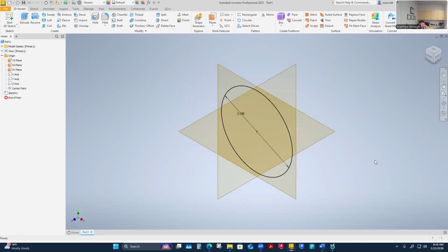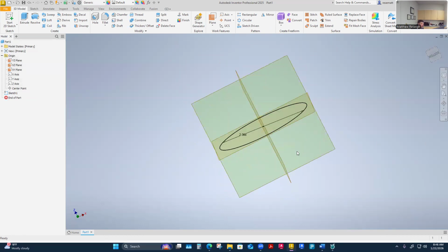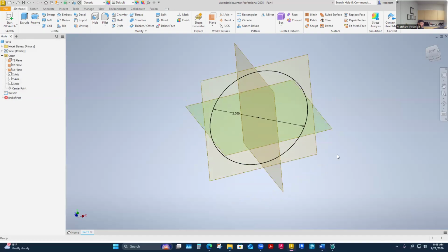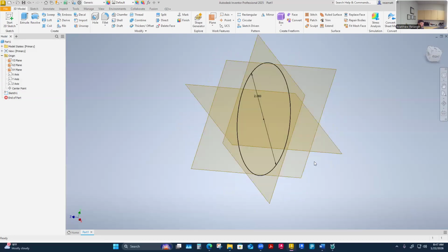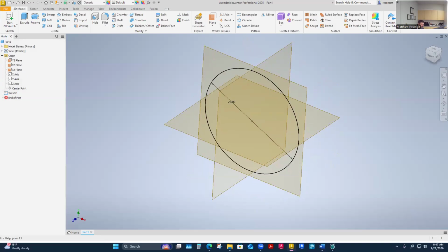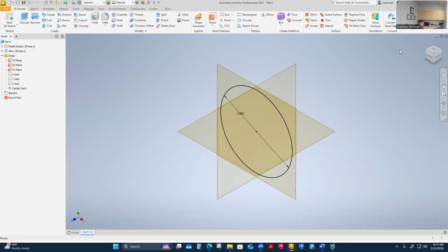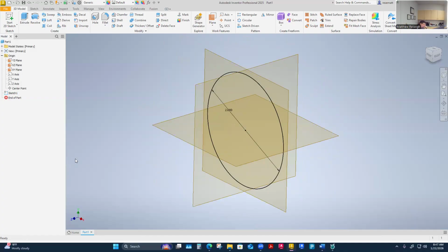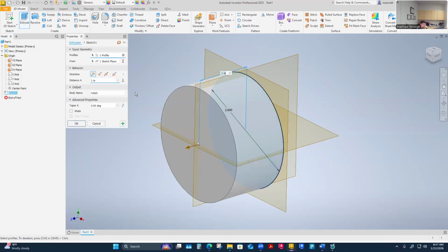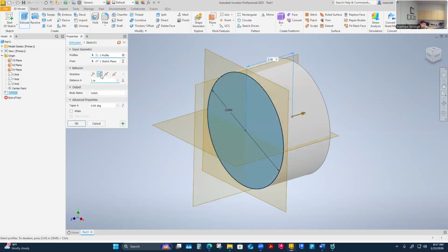If you click the home view, it is kind of like a 45, so you can see all 3 planes. This is helpful. I do use it, especially when I've lost my bearing on a big part, or I don't know if I'm upside down or right side up. Your planes do change color to help you know that you're on the underside or the top side of them. But if you lose your bearing, I always feel like the home button is a great one to reset, so I know where my bearings are in model space. Other than that, I don't worry too much about doing everything the same way he does in here. But yeah, I think it's just a 1/4 inch extrusion, and whether it's away from you or towards you is okay.